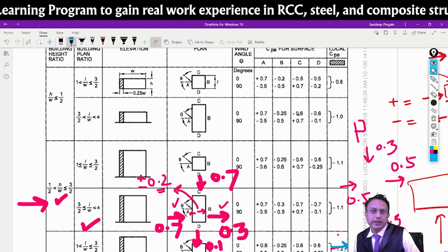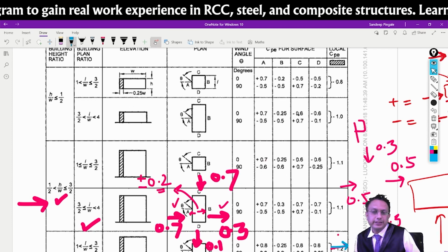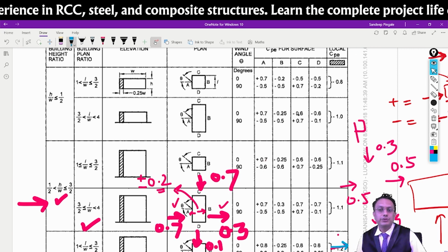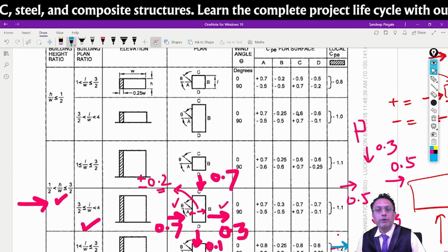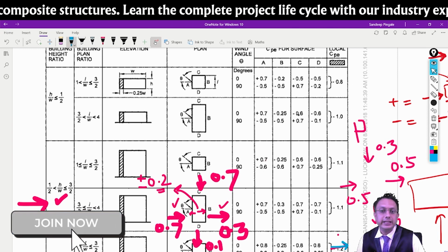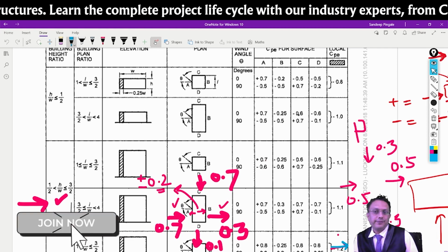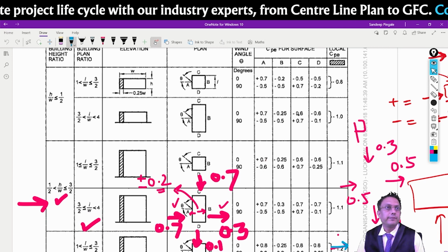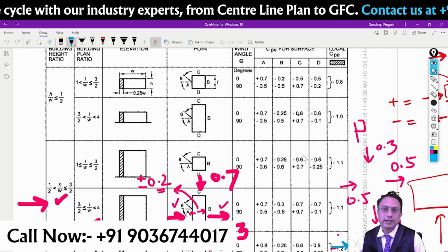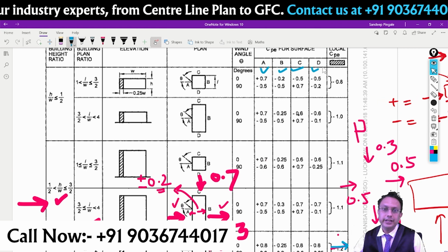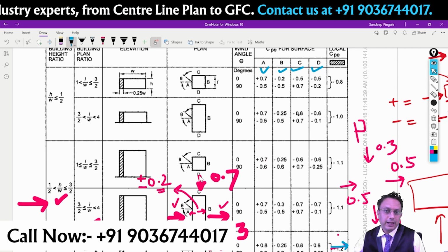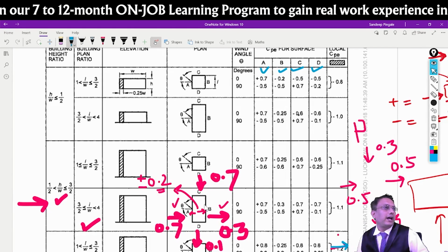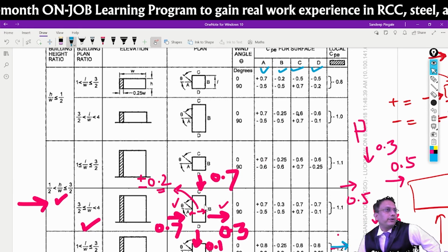Okay. 0, 90 degrees and all, actually let's not get confused in many other areas. Many a times certain consultants what they do is they take the maximum of the values. So instead of 0.7 and 0.1 they might take 0.7 and 0.7 on the C and D for the 0 degrees only. So that's what H is. A here, B here, C here, D here. So depending upon that, actually we'll apply the A, B, C, D. And once the pressure coefficients are final, then you will start applying to the actual structure. That's how it is.